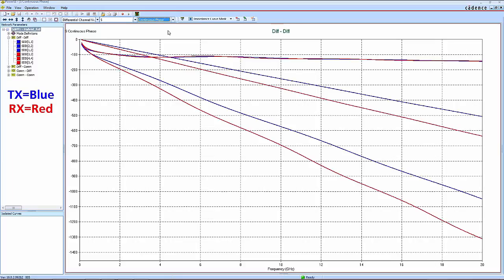But before we go to the next step of local simulation for the cut design, let's consider what these results tell us already. The phase behaviors tell us the reflection occurs dominantly, if not entirely, at the board side transition over the entire bandwidth. Since the board side reflection phase starts at about -90 degrees and decreases slowly with frequency, we know this transition is highly capacitive and localized to the board side transition.